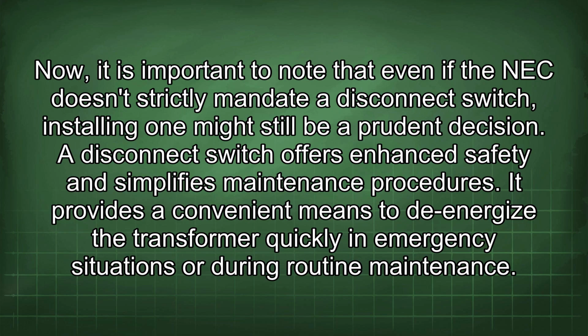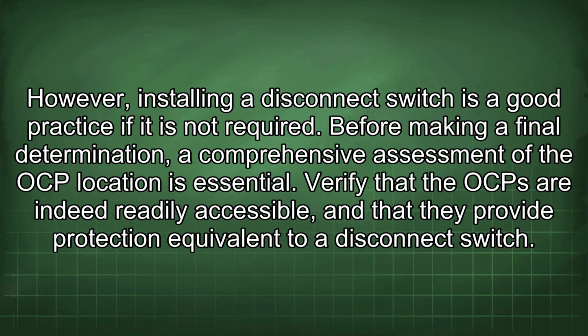Now, it is important to note that even if the NEC doesn't strictly mandate a disconnect switch, installing one might still be a prudent decision. A disconnect switch offers enhanced safety and simplifies maintenance procedures. It provides a convenient means to de-energize the transformer quickly in emergency situations or during routine maintenance. Installing a disconnect switch is a good practice even if it is not required.